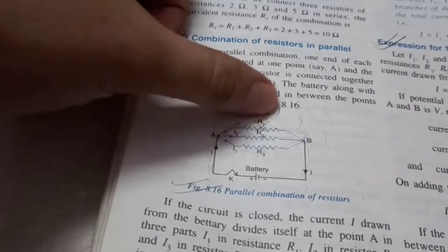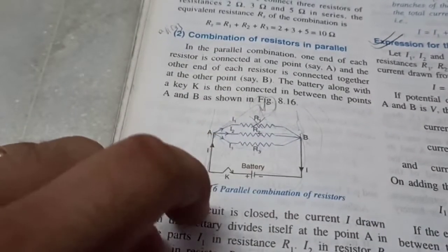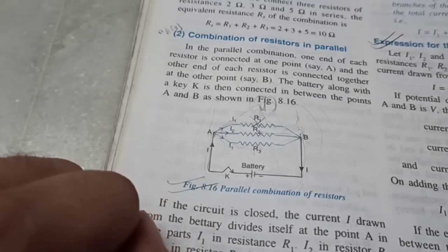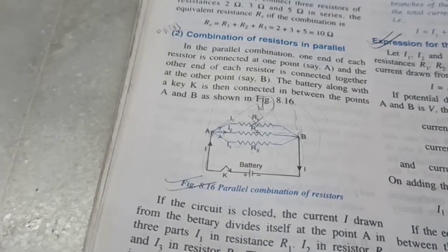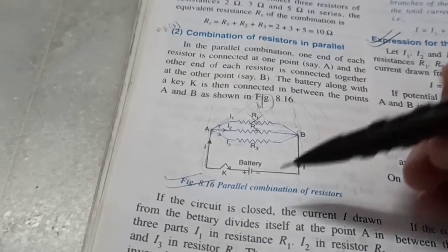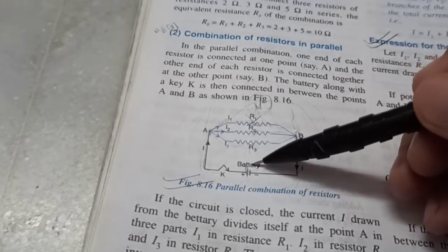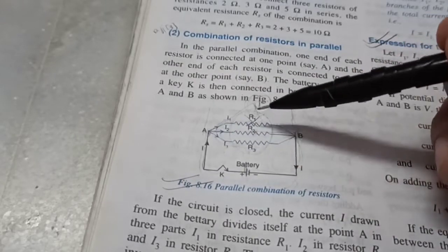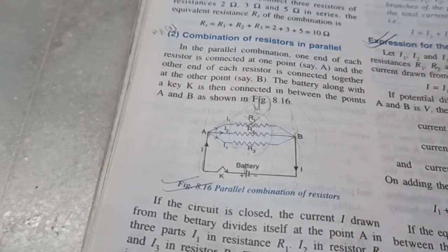Apart from the fact that the circuit is not broken easily, the other advantage is that it reduces the overall resistance. And you know that less the resistance, more current can flow through the circuit. So that's why all connections in our households are always connected in parallel, so that each has an independent circuit and also the total resistance decreases. Note that I have not talked about the internal resistance here, but if there was an internal resistance, let's say 0.2 ohm, then the overall resistance will be this, which is 0.9 ohm, which I just calculated, plus 0.2 because it is in series with this combination. So the final answer would have been 1.1 ohm.